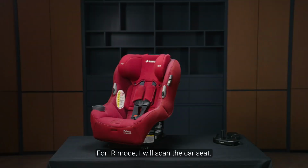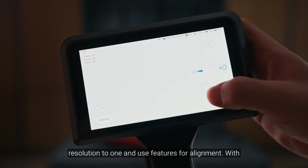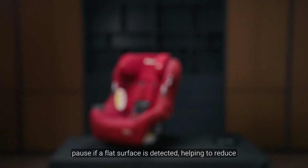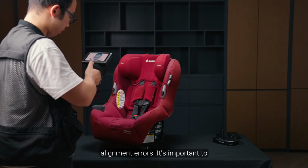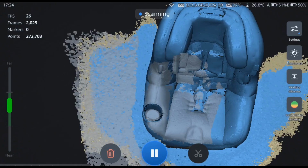For IR mode, I will scan a car seat. Based on its size, I will set the resolution to 1 and use features for alignment. With plane detection enabled, scanning will pause if a flat surface is detected, helping to reduce alignment errors. It's important to control the scan distance and move the scanner slowly.